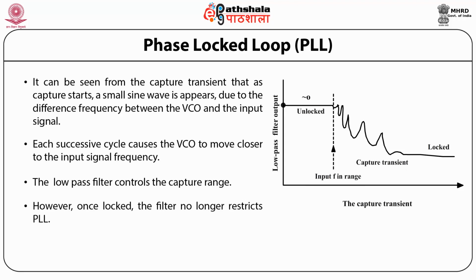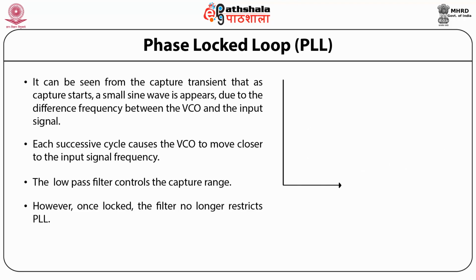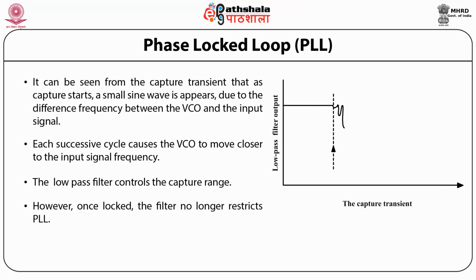However, once locked, the filter no longer restricts the PLL. The VCO can track the signal well beyond the capture band. Thus, the tracking range is always larger than the capture range.